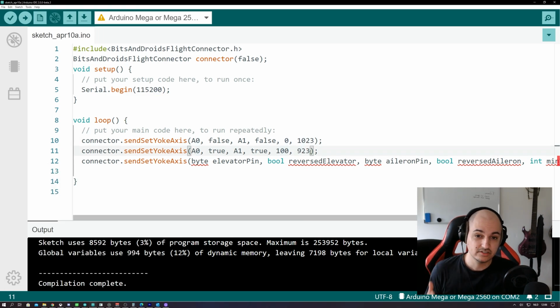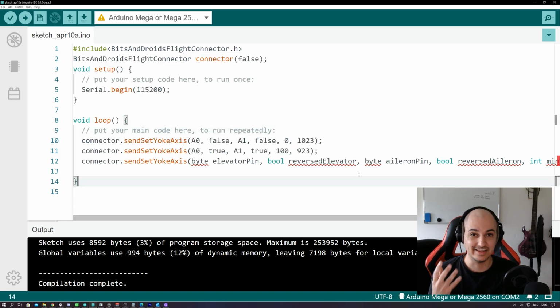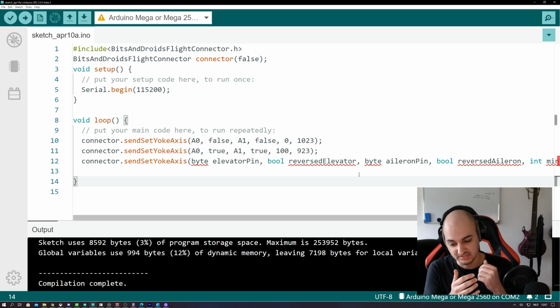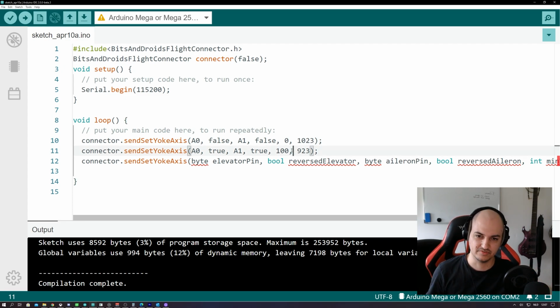What this also will do is, if you got this but you can use the full range, then 0 to 100 possibly results in negative values. So it maps it on an axis scale, so -1672, etc. So if your value is below that, I'm not quite sure what happens, if it returns 0 or if it returns a value that's lower than the range that's possible. So I'm not quite sure on that one. I need to figure that one out. It doesn't really matter that much. Just go with the one that works for you. So for me, it's 0, and 1023.